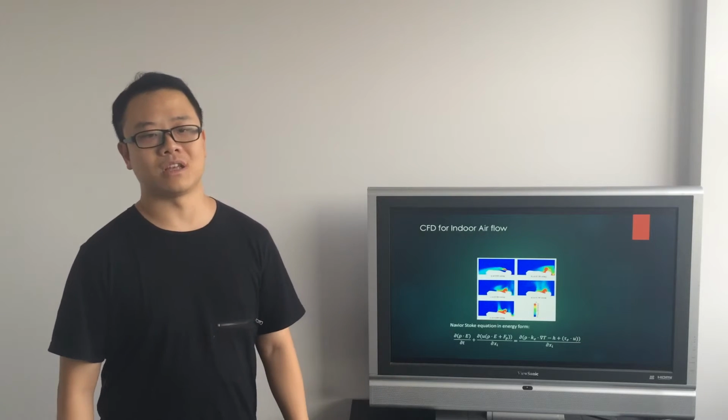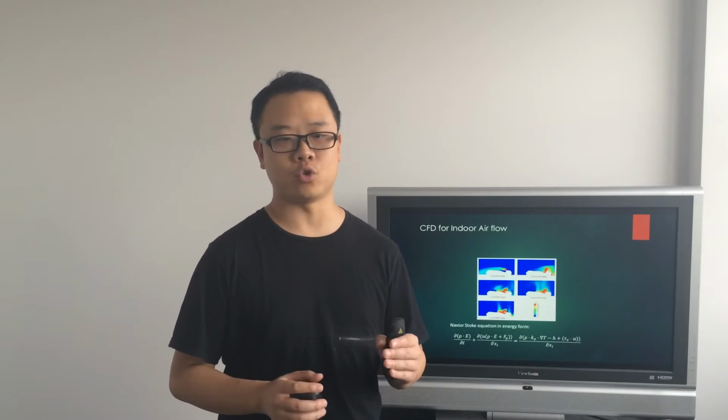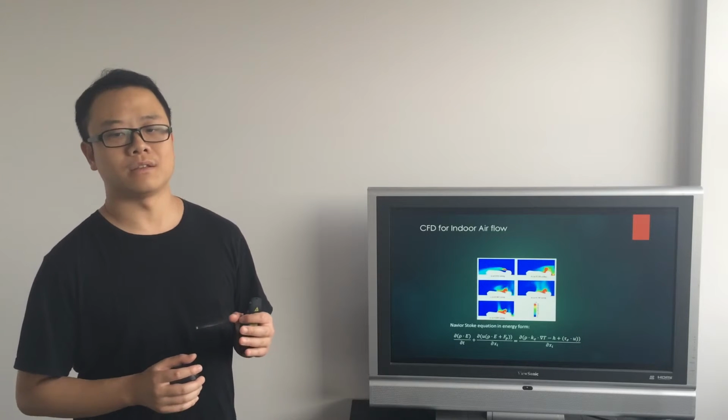This study used the energy equations to evaluate the momentum of airflow. The thermal condition is used as a term to share the energy with momentum. In this case, another key term was ignored in the simulation. Carbon dioxide flowing with air is a multiphase flow. There is a thin layer between carbon dioxide and air. This layer can be considered as a free surface boundary, and the surface tension should be added in this condition.